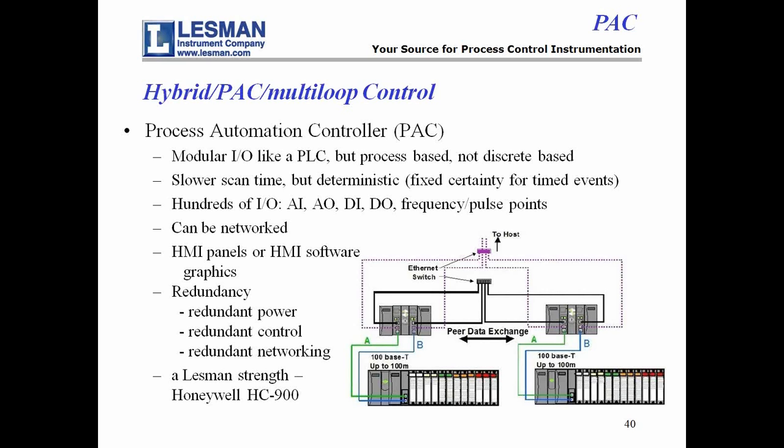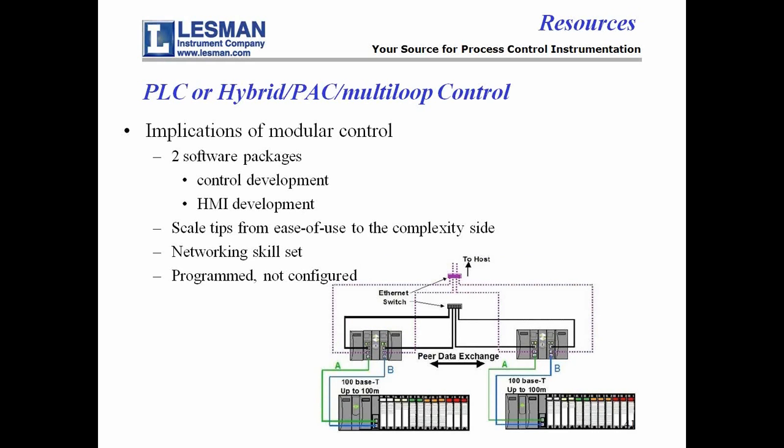The implications, by the way, going back to resources of modular control, is that typically you now have two software packages to deal with because these are programmed, they're not configured. You have a control development software package and you have an HMI development software package. So the people that are going to do this are going to have a much higher skill set typically than the people that just configure the individual boxes, loop controllers.